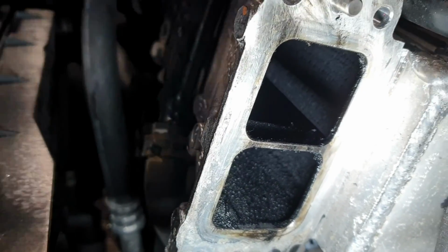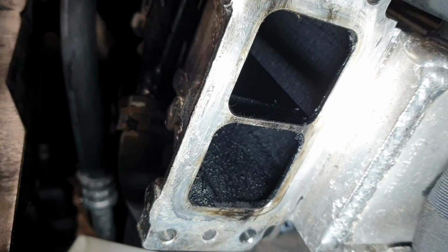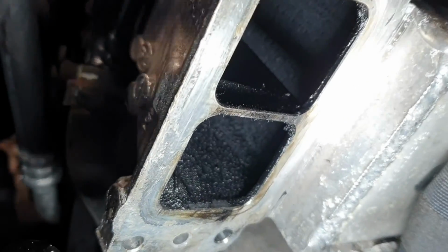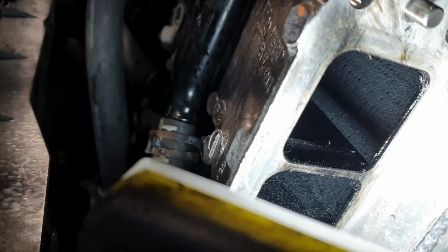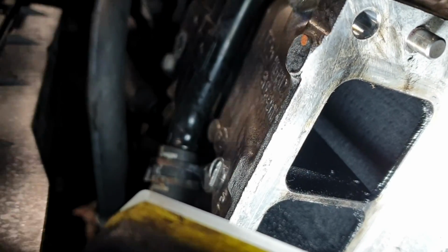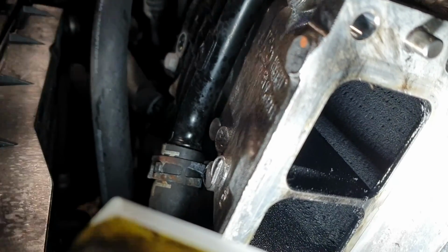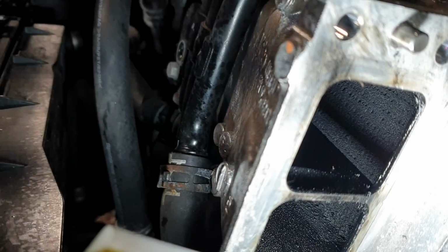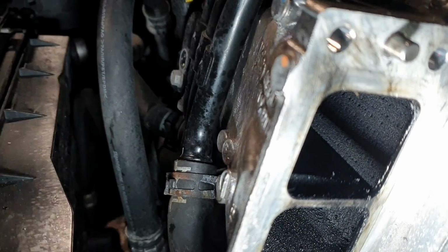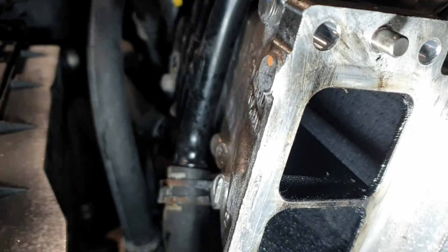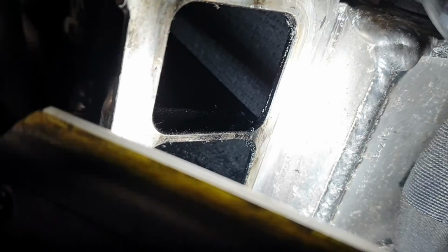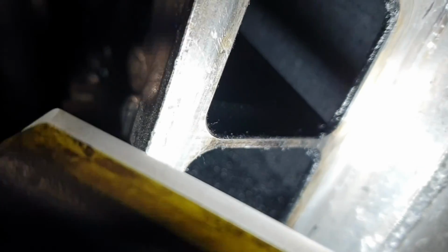I have just found that the intercooler or air cooler, the radiator orifices, are completely blocked inside. Look, it's completely blocked. But I don't know the structure of the inlet manifold, whether the air passes through these orifices of the air cooler, or there are different orifices for the air to pass to the inlet port or the inlet valve. But as I can see here, this is completely blocked. The radiator is completely blocked.